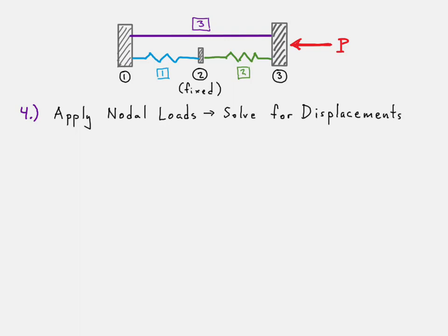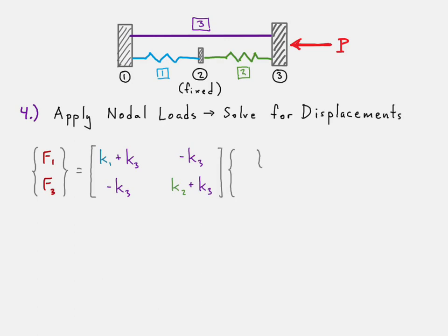Well, that's where we can actually solve. Once we get the nodal displacements, then we can solve for some other things. But the first thing we have to do is solve for those nodal displacements. So we write in our reduced matrix equation. That's the global matrix with the constraints applied and the rows and columns corresponding to that constraint removed.